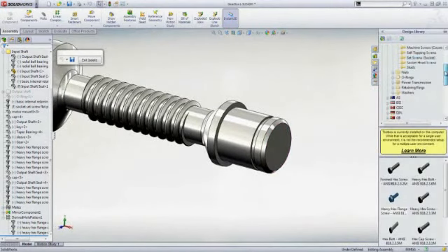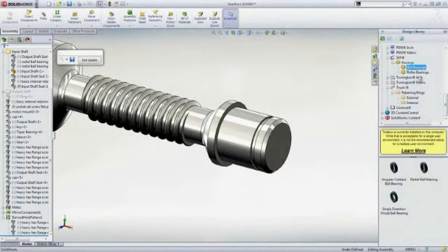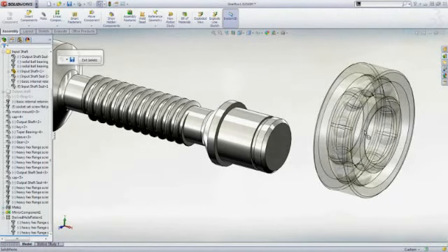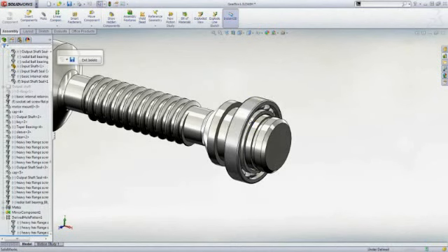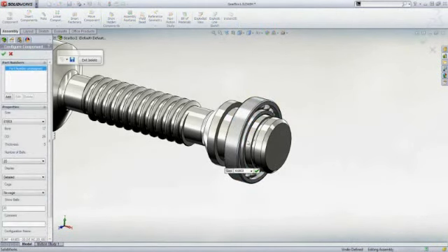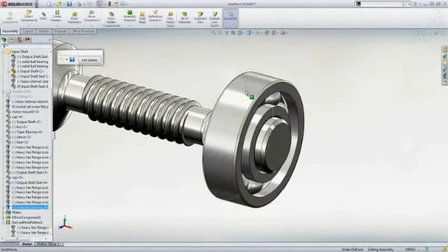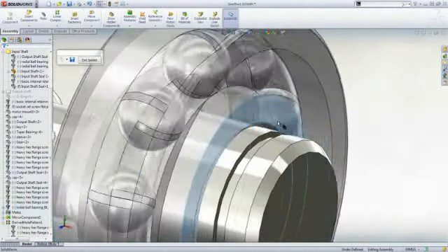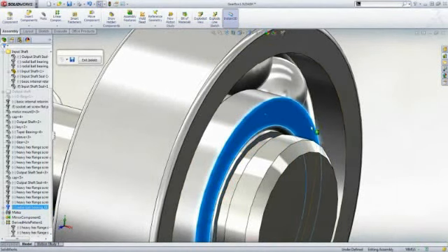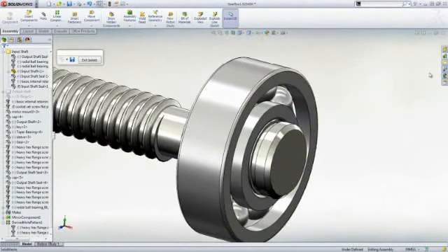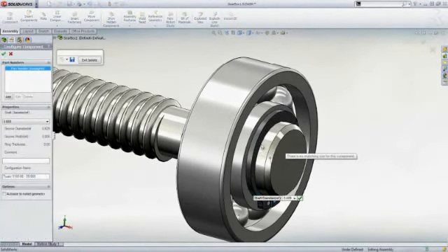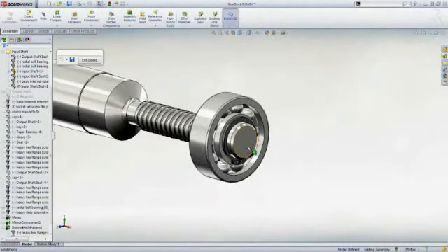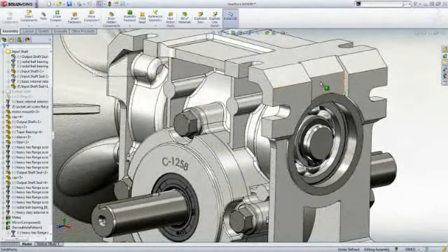Toolbox is not only useful for hardware items such as screws, washers, and nuts, but contains pins, bushings, keys, gears, pulleys, PEM nuts, snap rings, and bearings. These can be smart mated into position, auto-sized to fit upon placement as well. Upon placing and selecting the correct bearing, we can smart mate it to the snap ring groove. Then we will assemble a snap ring to hold the bearing in place. Finally, we will assemble the shaft cover from the File Explorer and smart mate it into position.